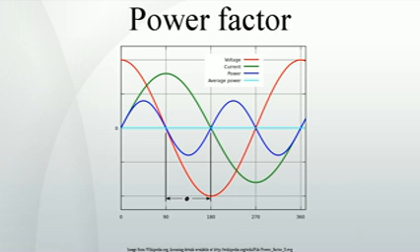In linear circuits having only sinusoidal currents and voltages of one frequency, the power factor arises only from the difference in phase between the current and voltage. This is displacement power factor. The concept can be generalized to a total, distortion, or true power factor where the apparent power includes all harmonic components. This is of importance in practical power systems that contain nonlinear loads such as rectifiers, some forms of electric lighting, electric arc furnaces, welding equipment, switched-mode power supplies and other devices.